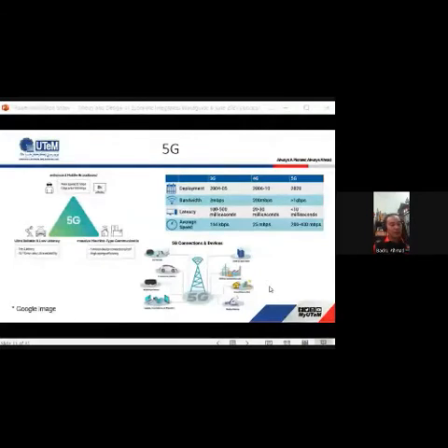So some frequency bands already exist, for example the microwave frequencies which have the L, S, and also C band. These frequencies are ready to go, I would say, for 5G. But they can be exhausted because of these applications. So what's next? We will look at a higher frequency region than L, S, and C. This is the millimeter wave frequency range, which is unlicensed and unused.